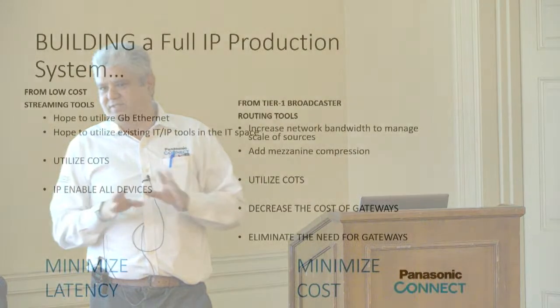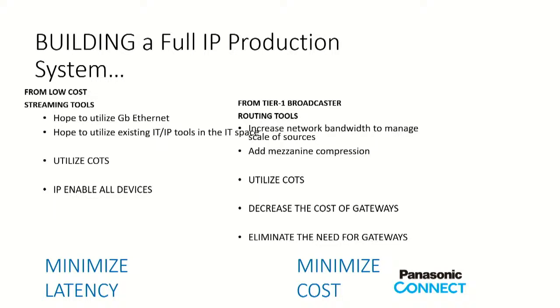So another issue was latency. In the video world, latency is an enemy, particularly if you have an iMag in a church or in a boardroom. With iMag, your lip sync issue will be a problem. If you compress the video, you have to uncompress it on the other end. That means you encode it, you have to decode it. The encoder and decoder cost latency.